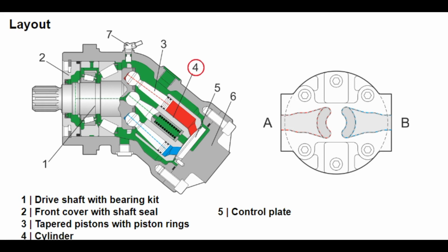Due to the bent-axis design, torque is produced directly on the drive shaft. The pistons exert minimal lateral force on the cylinder, which reduces wear, increases efficiency, and improves starting torque. The port plate holds the rotary group in the housing and passes hydraulic fluid through 2 channels. The hydraulic motor can also be equipped with a speed sensor as an option.